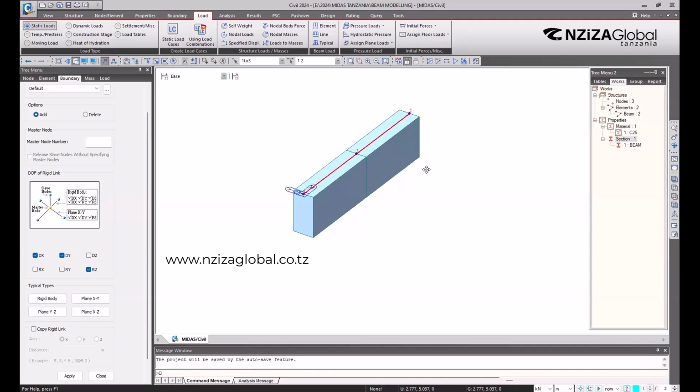So, is it clear? I'm saying that for these construction stage loads, infrastructures like a bridge are not constructed in one day. The first phase, maybe it's for foundation and abutments, right? So there is no need of considering the whole loads which will be applied on the bridge at the same time. We'd be exaggerating the design. At the first stage, we will consider the loads that we'll be having there.